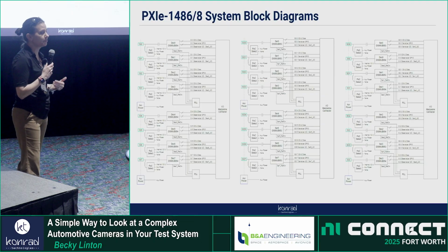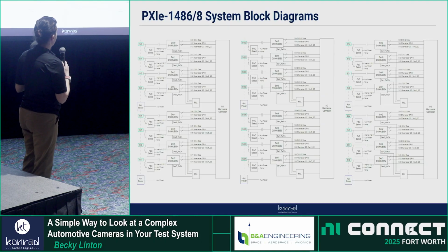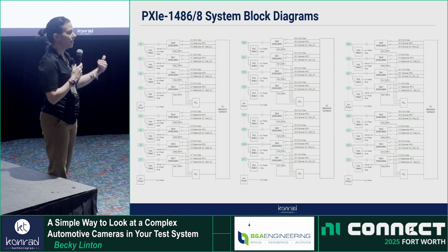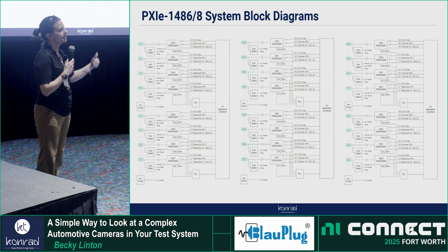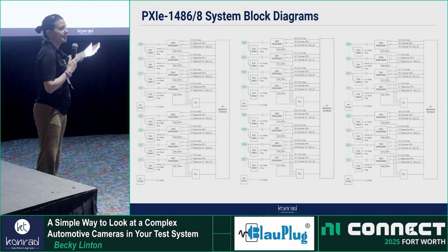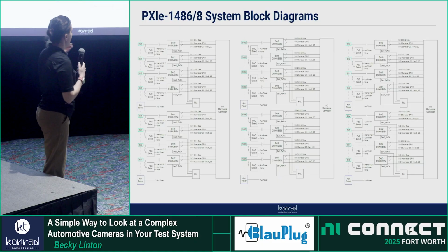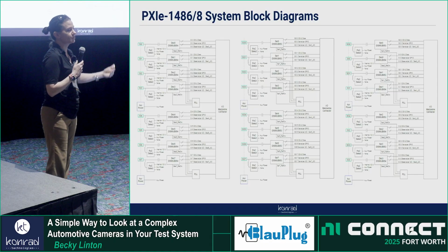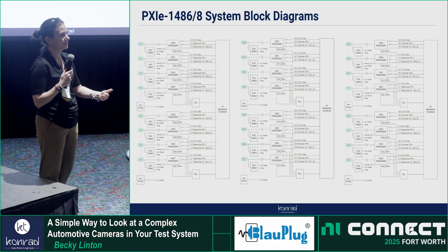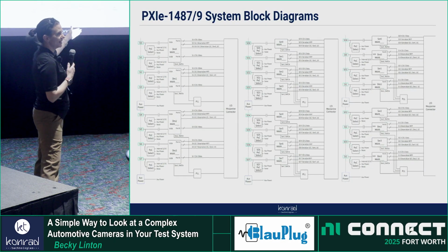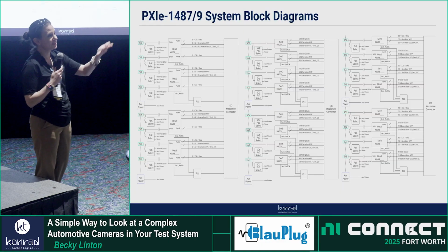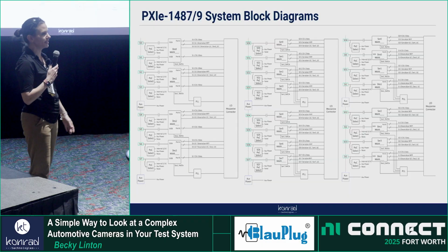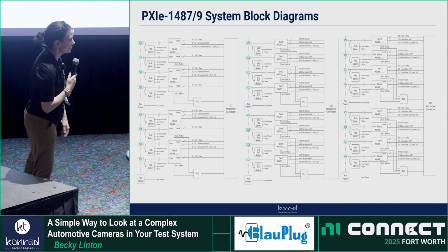We could have done channel pairs, but then we had to discover and implement aliasing, or I forget what GMSL calls it, but it's the same thing. Basically, we have to get through programming the serializer and imager and give them a different I2C address, because otherwise is channel 1 failing or channel 2 failing? And so it's just extra stuff we then have to maintain per channel that, had there been an independent one, and I know that was probably a cost solution, or space, could have been either. Space, yeah. But that was something that was a little bit harder and we wish would have been just examples and had more stuff for.